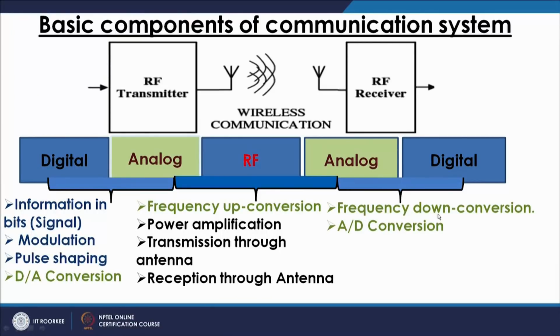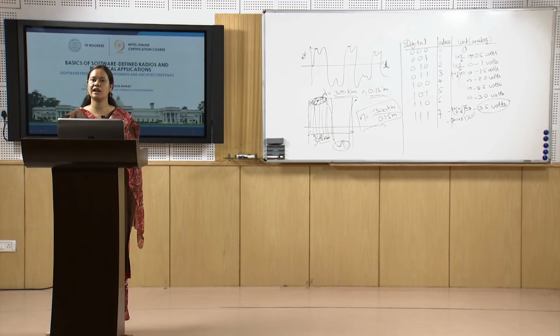Now frequency down conversion is a step which is the opposite of the frequency up conversion. As I showed you earlier, by using a nonlinear mixer, we can select the subtractive component, RF minus LO frequencies, and the frequency will come down to the analog domain. Now we have our analog domain signal which we had in the transmitter section. So the same information we have here in the receiver section. Now we want to extract our digital data from this information.